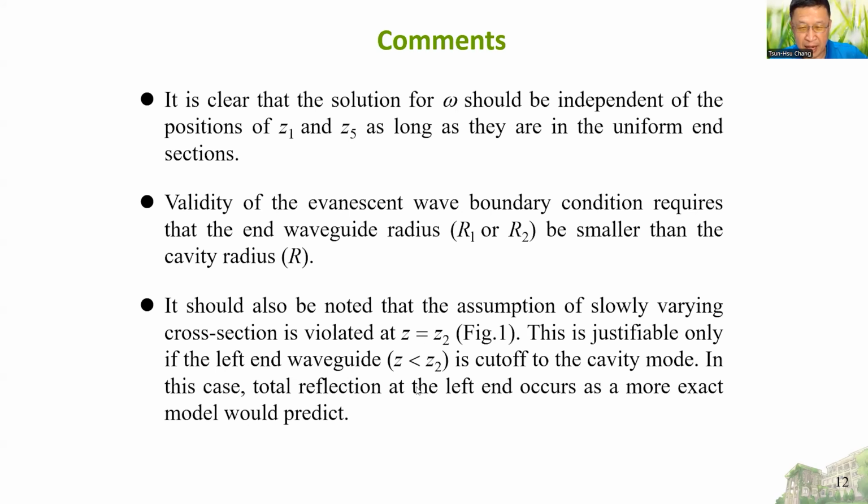This statement is a little bit complicated to understand, but just imagine the left-hand side is a cutoff section and the wave is evanescent, and it's uniform. So even though it's not a slowly varying cross-section, it's still acceptable. Not much difference. But if we want to consider this effect, we will introduce a new technique called modal analysis. It will excite more than one mode. Modal analysis later on.